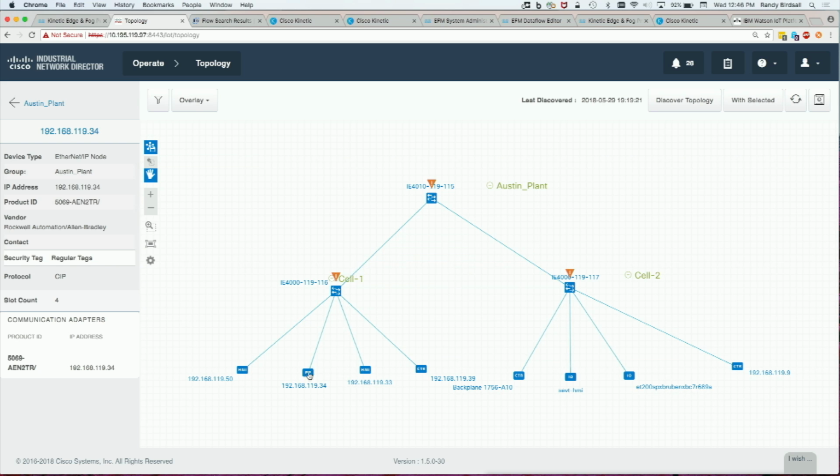But all of a sudden, this particular PLC down here that we pulled up, this Rockwell, is having an issue. And we need to get support from Rockwell to come in and work on it. Typically what would happen is they'd reach out to IT and say, hey, we need to get VPN access to our DMZ for this Rockwell guy. Then you need to set up some ACLs to allow him to get access to this and only this machine. Can you help me do that? And then they have to figure out how they communicate about enabling that.